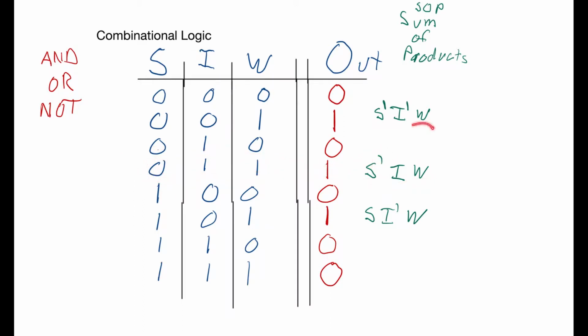So now that we have all the ones and we wrote down these terms, all we need to do, and by the way, this is like multiplying, and you know in math when you write A5 or 5A, that you multiply the 5 and the A together. That's the same with this, but our multiply operation is the AND operation. So this is these three inputs ANDed together. And finally, that's the products, by the way. So here are our products.